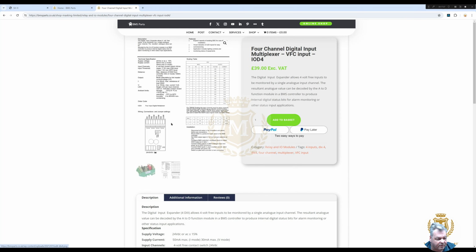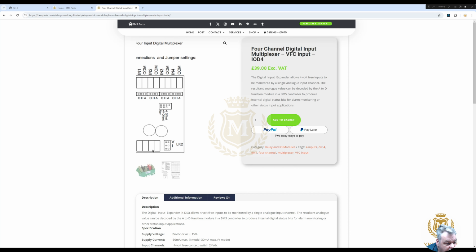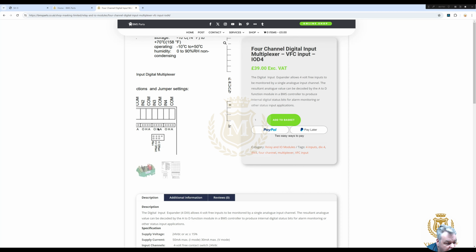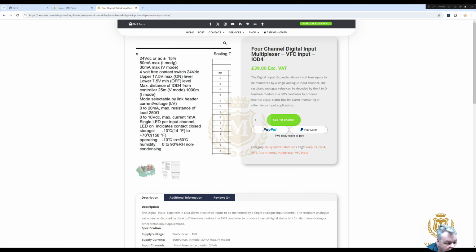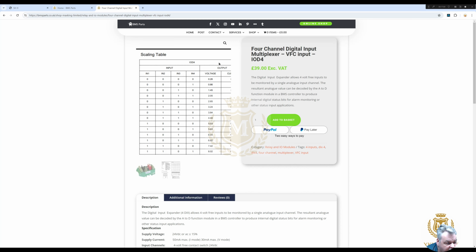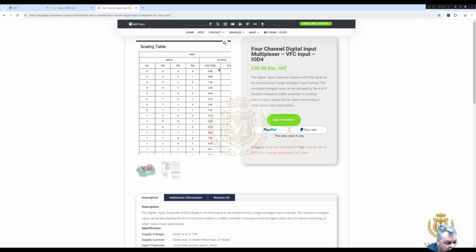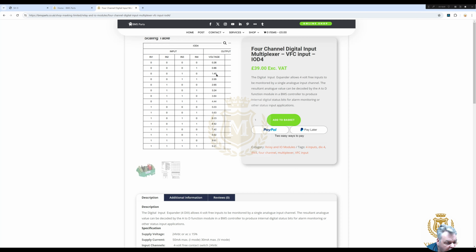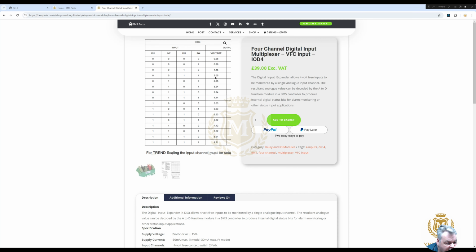Can we bring up a sheet there? So there's my 24 volts supply and my 0 volts on my out voltage, and we've got in 1, in 2, in 3 and in 4, and depending on the inputs it gives you a voltage coming out. So no inputs 0.26, input 4 0.86 volts, input 3 1.45 volts, input 3 and 4 2.05 volts.